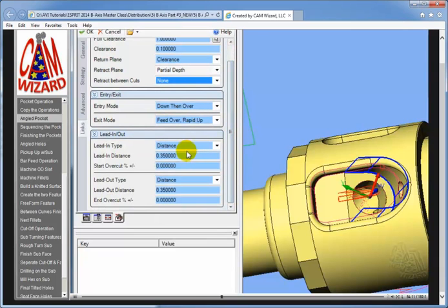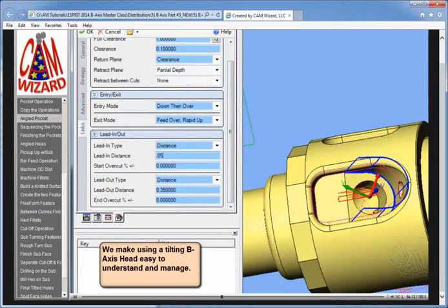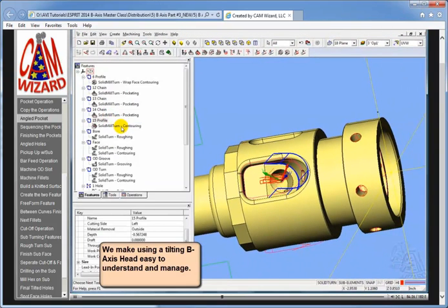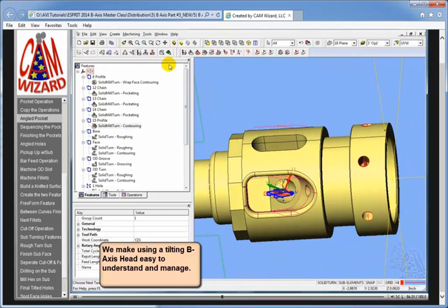Alright, lead ins, lead outs. I don't need a lot of room here. Let's go 50 thousandths. And then I will overlap a little bit on the tool. So I'll let the tool overlap by about 10 or 15% of the cutter. Let's hit our OK button and let's see what we get. What we end up with is a nice contour pass that goes around and cuts the part. Let's run a simulation on that.